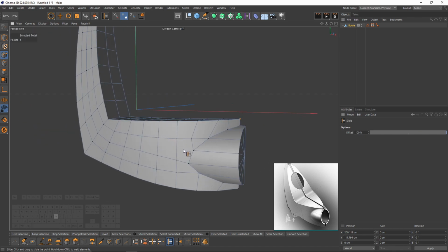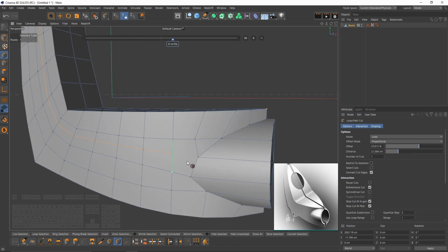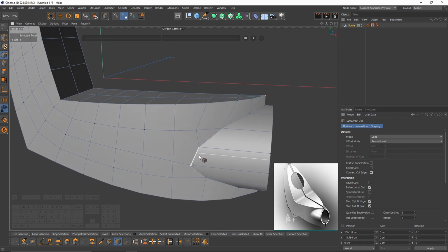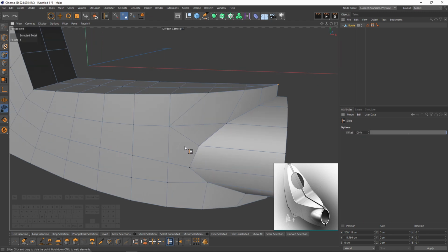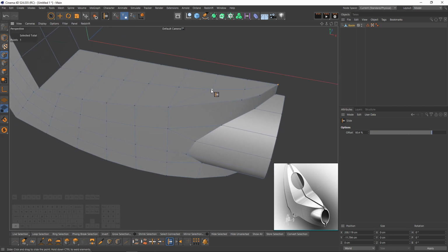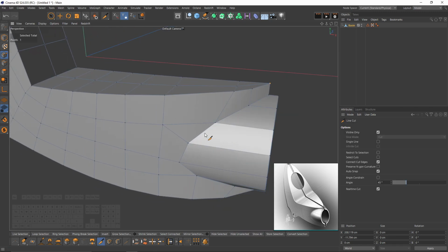I can create a new path all the way along to the top. I don't think it is going to be any beneficial. It's going to just increase the polygon count. So we need to find something else. Why don't we just weld these to that one? Then line cut, create any path, and finish it right here.